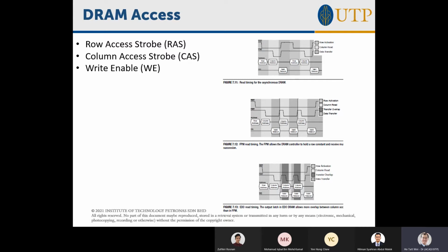Because normally the DRAM is actually a chip, so your signal will come from another chip. You're actually going onto the board, so the wires are really long compared to the wires on the chip, so it's going to be really slow. And what makes it even slower is that you've got 16 wires in parallel going in one go, so those wires will have inductive coupling and capacitive coupling, so you cannot run them too fast. This is what makes this kind of asynchronous DRAM really slow.